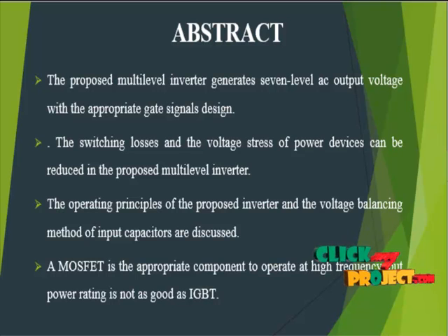The input voltage is divided across three series capacitors C1, C2, C3, hybrid with the MOSFETs. We are using four diodes, and the voltage is sent to the output terminal by an H-bridge of MOSFETs. The proposed multi-level inverter generates the 7-level AC output voltage with the designed gate signals.